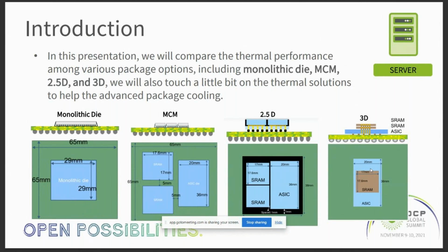Thanks. So Eric, I have a question about this 3D. The 3D connection between the chiplets is either through the micro bumps or through hybrid bonding, right? So how do you take into account the effect of the micro bump, and once it's hybrid bonded, in your thermal models? How would you model them?